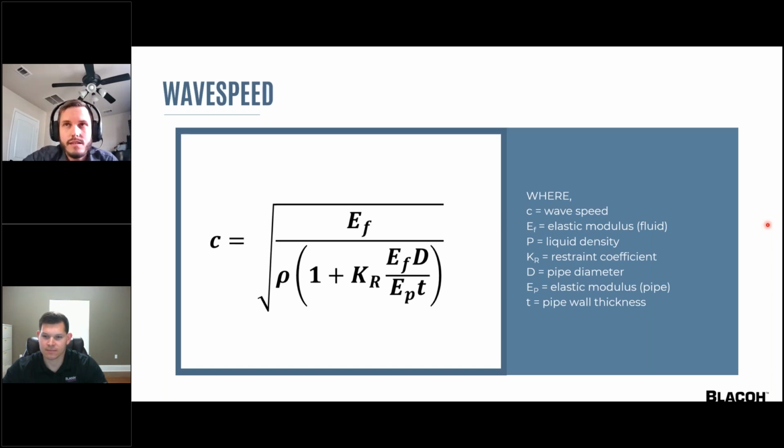Energy is lost in deforming the pipe, which will lower the wave speed. Air entrainment can significantly affect the fluid modulus also. All these variables need to be taken into account when making an accurate hydraulic model. However, practically, especially in the design phase of a project, they can only be estimated.